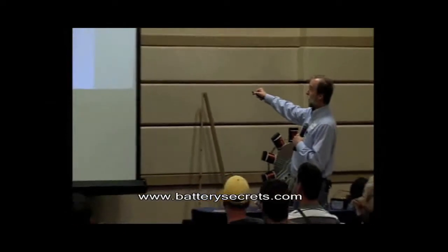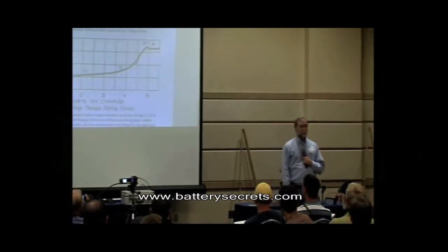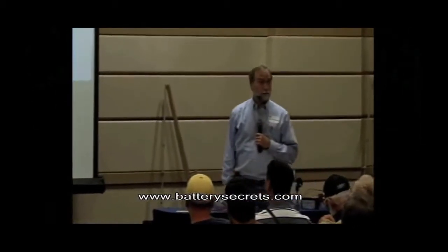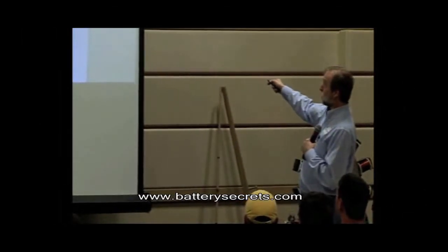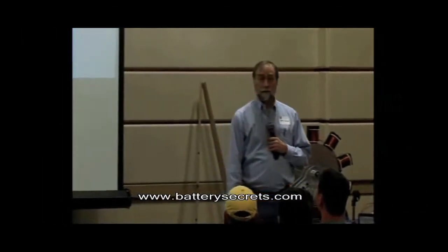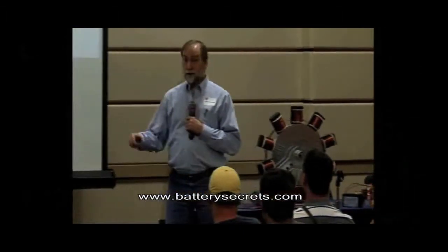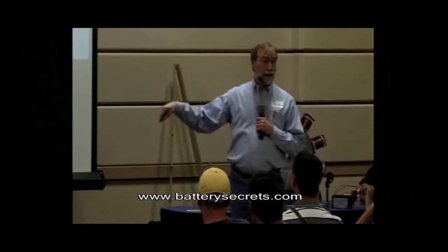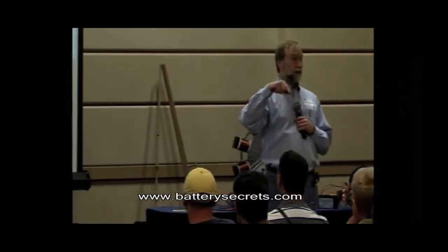So, at that point, anything more that you put into the battery can't charge it anymore because the battery is 100% charged. And so what can happen if you continue to charge it here is that the machine starts running as an electrolysis cell. Don't forget, what it's doing is breaking up those water molecules that we made. We're putting the hydrogens back into the solution, and we're taking the oxygens and plating them back out on the positive plate. That's what chemically charging the battery looks like.